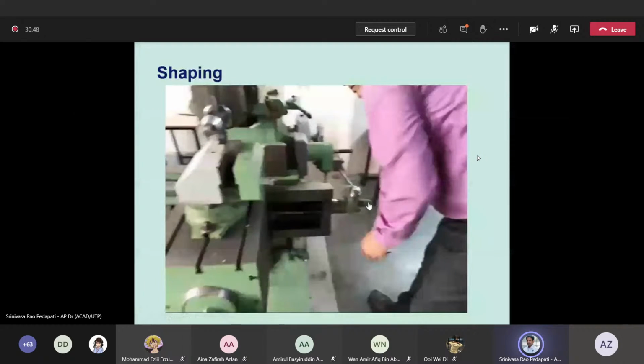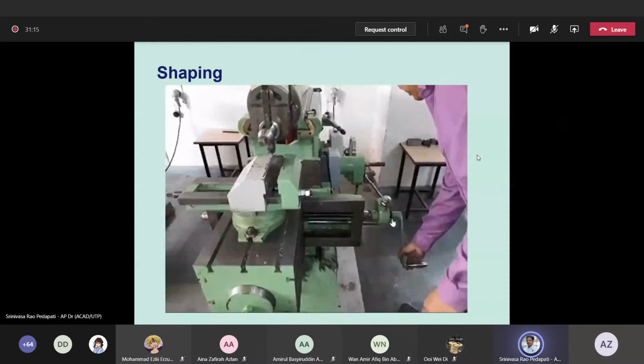One which he is adjusting here is what is called feed rate. That means the tool has to move along this direction. Say, for example, the reciprocation is the x-axis, and the other side is the y-axis. So it has to move along the y-axis to cover the entire surface of the cutting. So that is the feed given automatically or by hand. The feed rate is what is changing. The reciprocating is depth of cut.